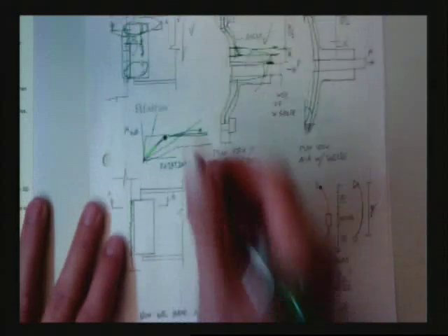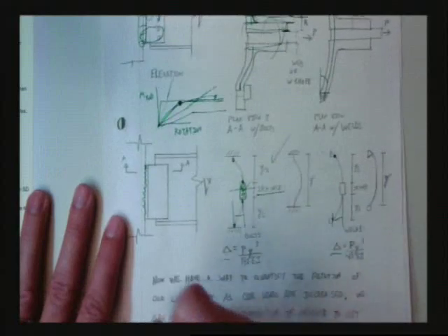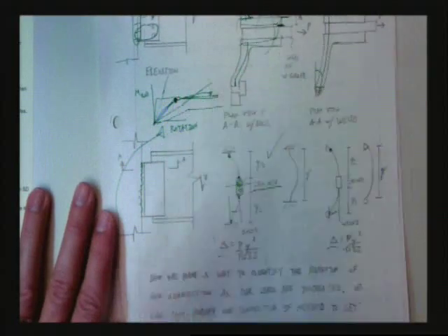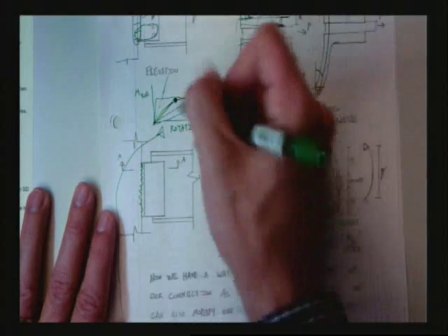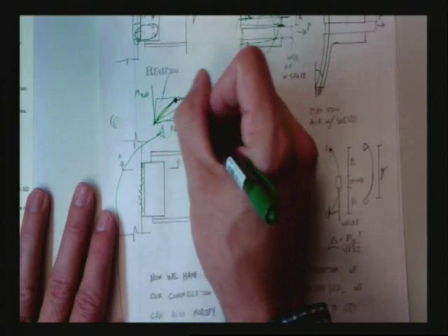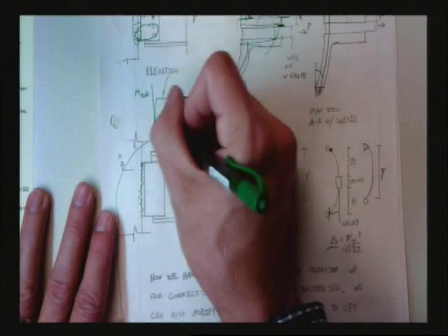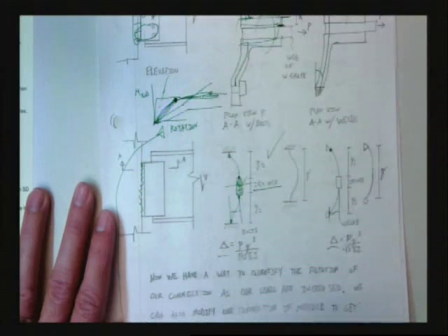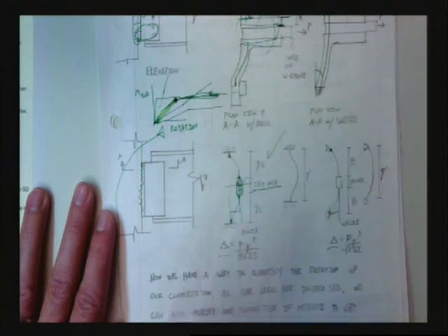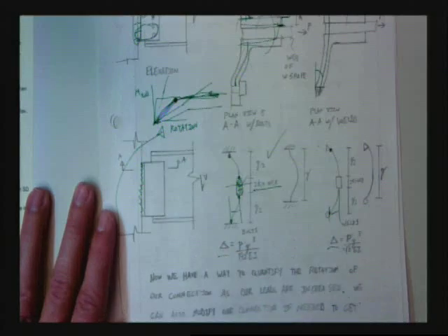Awesome. We assume this rotation is linear until we get to yielding of our connection angles. And that's really just explaining this. We realize that it's this nonlinear performance, and we're going to assume a single linear line, and then it's going to be bilinear. It's going to be elastic plastic. That's our assumption. You with me?